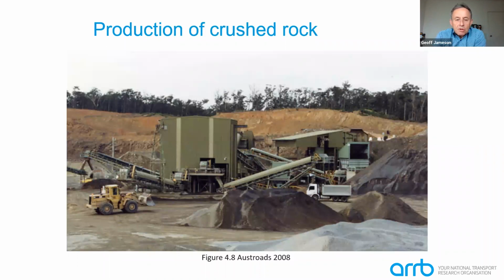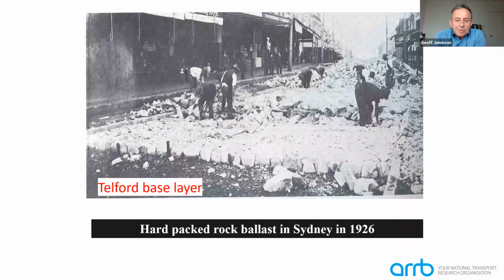So in terms of crushed rocks, they are manufactured at a plant. They could be split into different sizes and then recombined, or it could be what's called a crusher run, where the crusher is just set to give you a desired grading and you don't sort it into different sizes and recombine it. Granular materials weren't always like this in terms of being crushed and nicely graded materials that we use today and placed mechanically. There were times when granular materials were hand placed and larger pieces of aggregate were used. So it hasn't always been like what we use today.